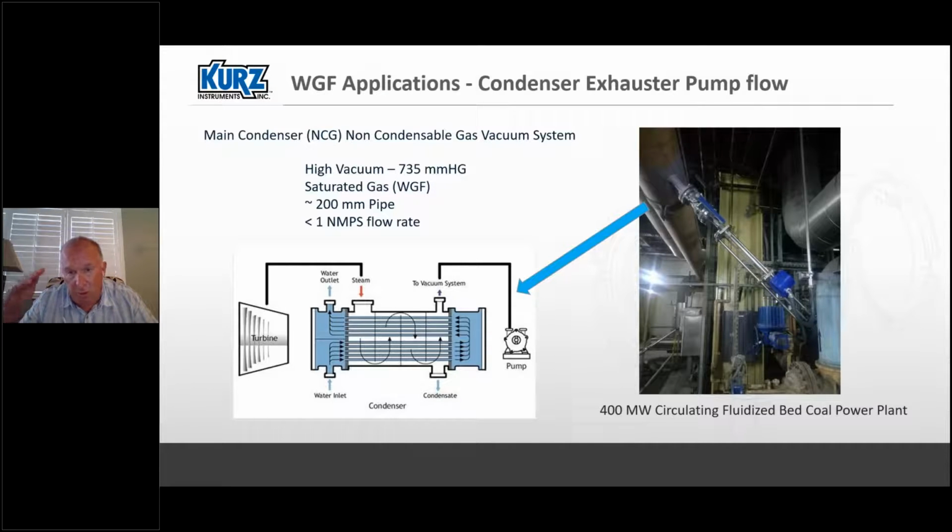You'll notice the sensor, when possible, should be installed from the bottom, usually a 4 o'clock position. This allows any water droplets that hit the probe to condense and drip away from the sensor. You could put it at 6 o'clock in this duct, but then I would be the drain plug when we pulled that probe out. So we prefer a 4 o'clock or an 8 o'clock position when possible on these wet gas applications. Obviously on vertical stacks, that's not possible, but we're still seeing very, very good performance.